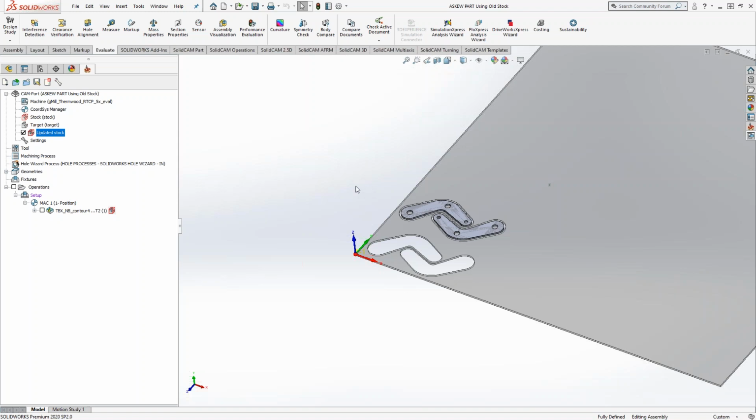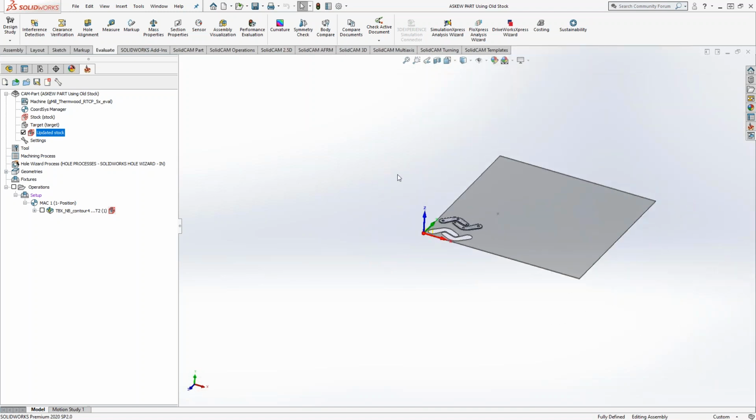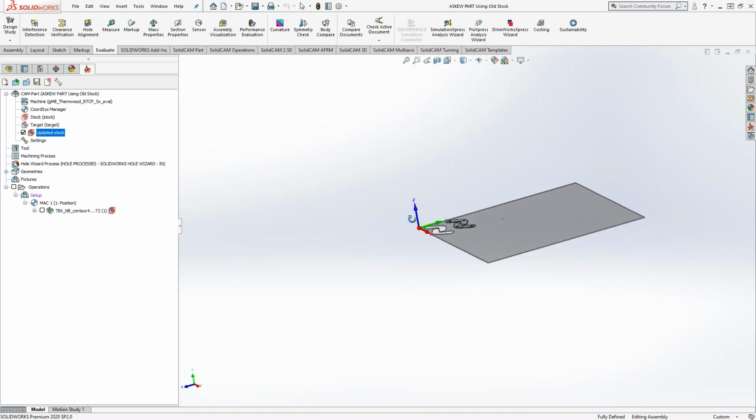So it can be a little confusing if you don't remember what coordinate system to output under, and that's the mistake I kept making here. But once you go into the facet model editor and choose the proper coordinate system to output to, those values translate in whatever axis you're working in, and those are the values you want to shift and rotate to get this. So this is actually the same STL file generated by the previous SolidCAM file, but with the proper shifts and angles to get it to line up with this coordinate system.